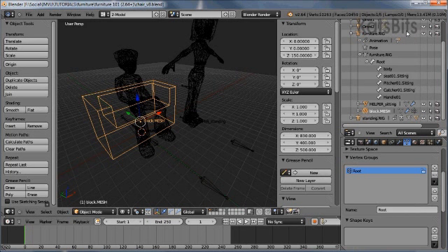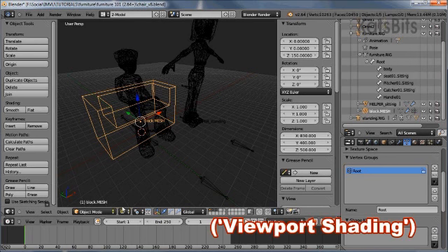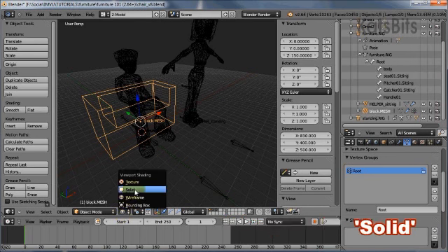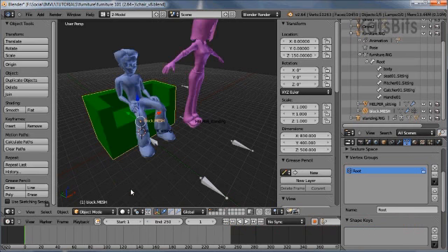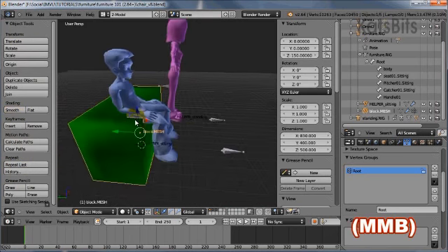One final step before we get this ready to export to IMVU is to apply smoothing. So with the mesh selected, right mouse click, click solid. The shortcut key for that is Z. And over in the tool panel on the left here, click smooth. You'll note that the mesh goes all mushy.